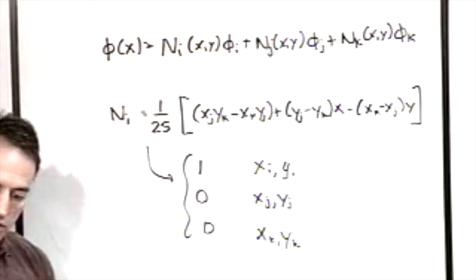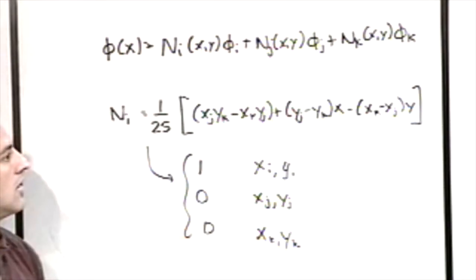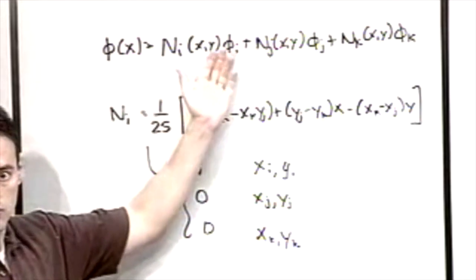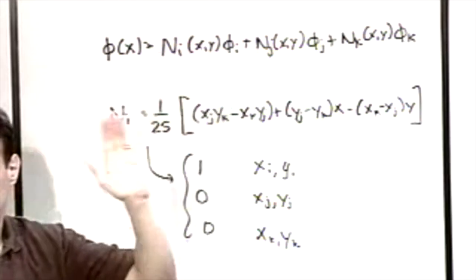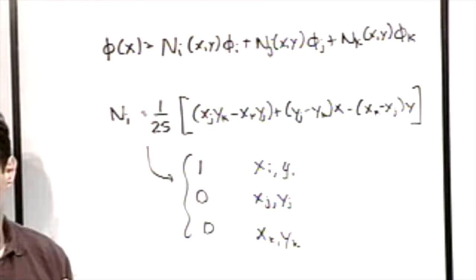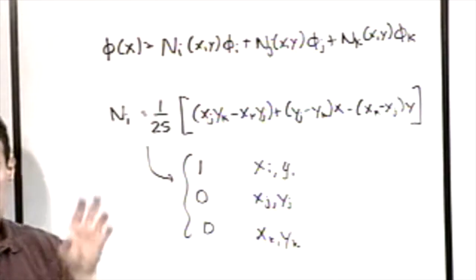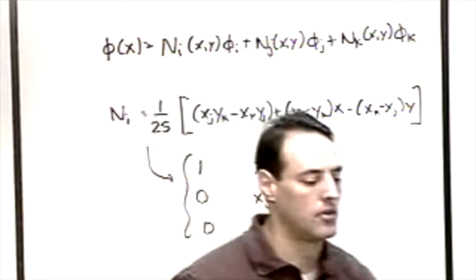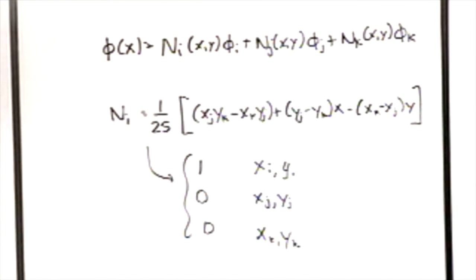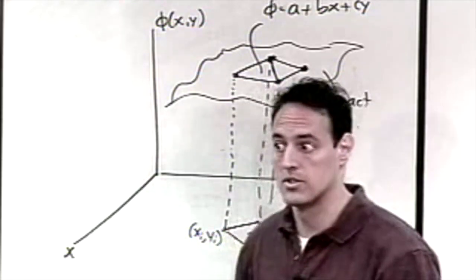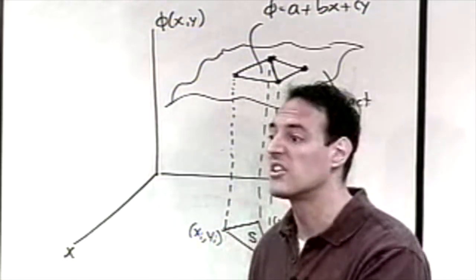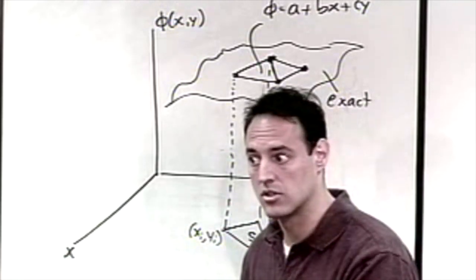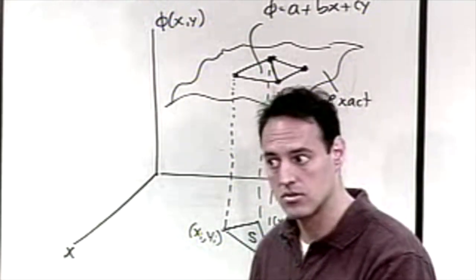So the idea now is you have a method by which you can algorithmically construct these interpolating functions. So what we've done is we've gone through 2 parts of the list. We've said that for any solution surface, we've got to figure out how we want to represent it, essentially, by using a simplex, complex, or multiplex finite element discretization on these triangles, for instance, in 2D.